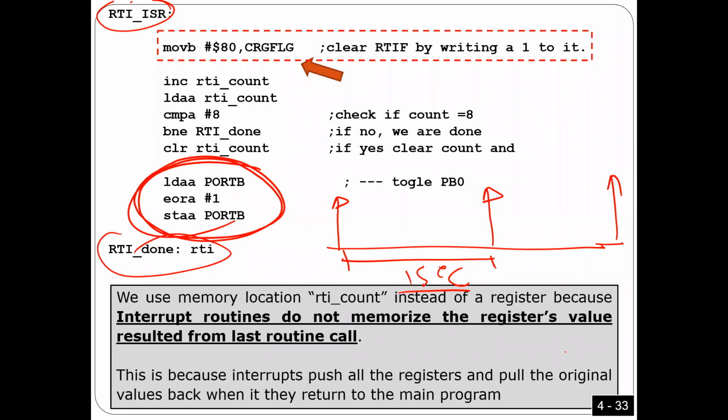Okay, guys. So the way I'm going to do it here is I'm going to count. This is interrupt 1, after 131 milliseconds. This one is another 131, another 131. So in the first interrupt, I'm not going to do anything, because it's just a 131 millisecond base. I want to toggle the LED every 1 second.